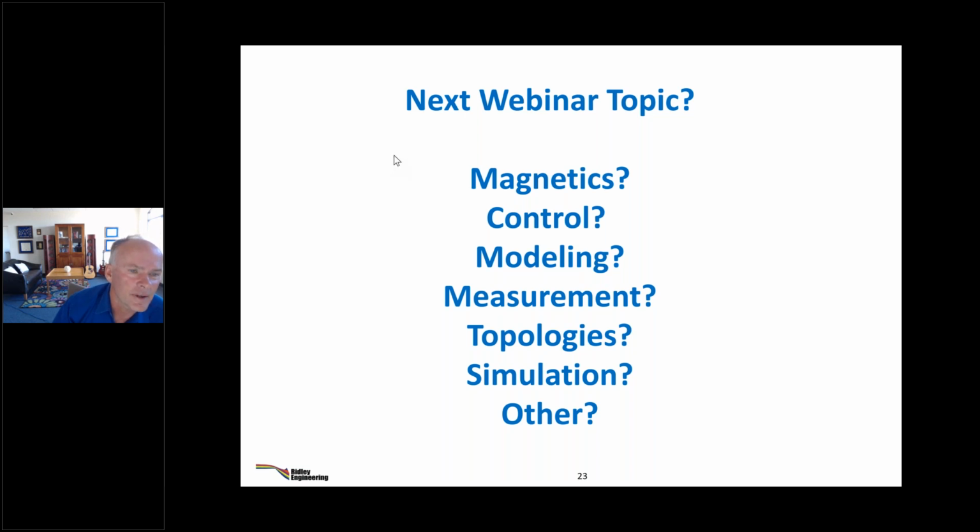Calculation of the design circuit is all done through Nicola Rosano's impedance curves and scaling techniques. Watch our previous webinar on LLC design. You'll find all that, and then you'll find a link to the book as well. Matthew Kalicharan, I think you're talking about the proximity losses. You're solving Dowell's equations for foils, wires, Litz wires, and so on, and comparing the results.